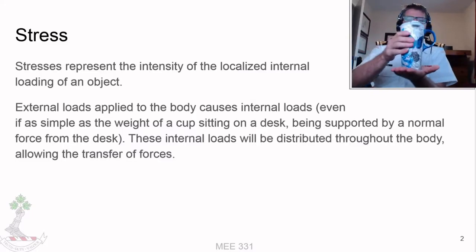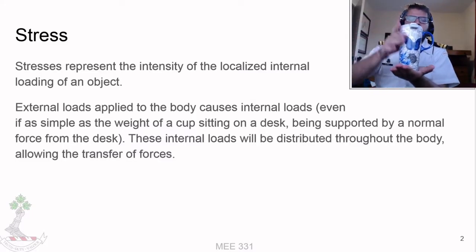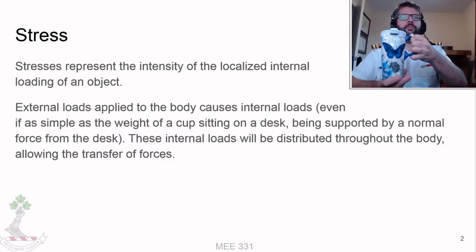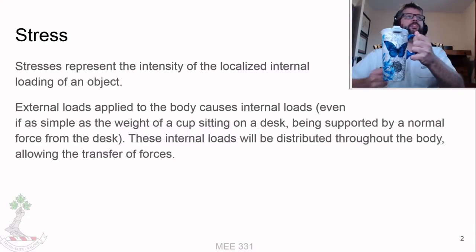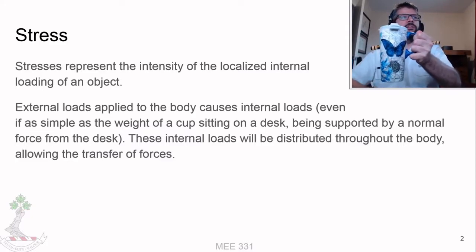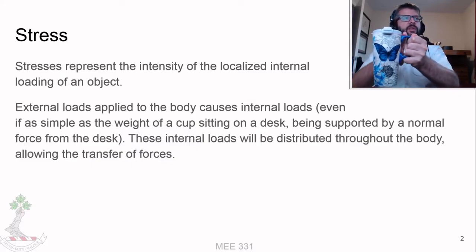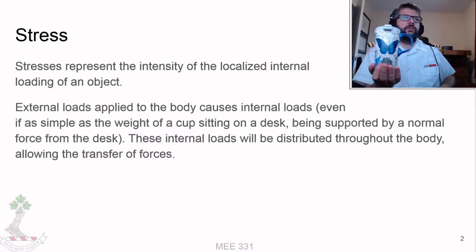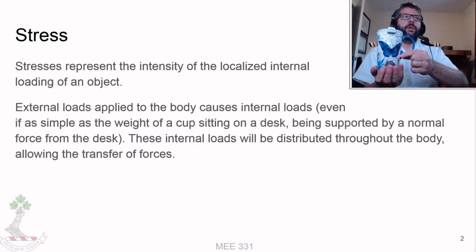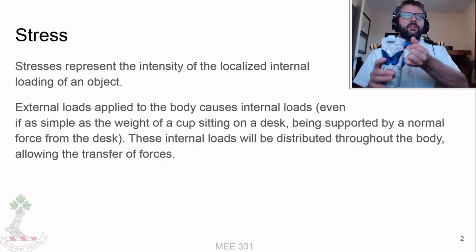So, whether it be gravity, whether I'm pushing it on here, whether I'm holding it from here, there's a different distribution of the forces that arise based upon where the external loads are applied. If I'm holding it by the handle, then you're going to see different stress levels in the handle than you would if I was just doing this, because in this case the handle itself only needs to hold the weight of the rest of the handle, whereas here it needs to hold the weight of the entire cup and all the coffee inside.